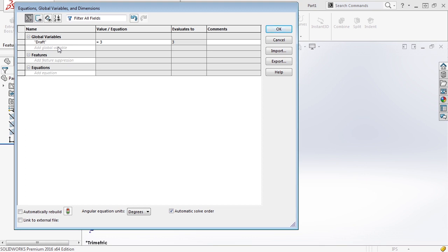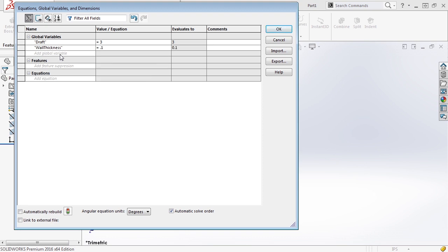So moving forward, there are really a few other things that we must know as we're going through. The first is going to be wall thickness. And I really like to set this, and I'm going to set it at 0.1. It's rather thick. We're not really concerned because we're not physically making a part. But that way I have a nice number that I can use, and the next part makes a little bit more sense.